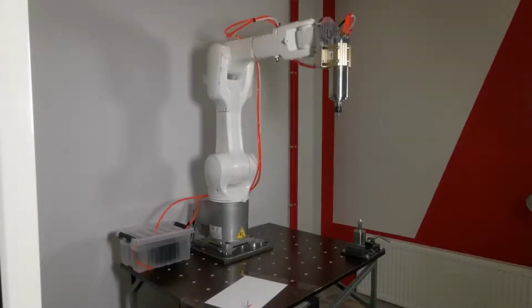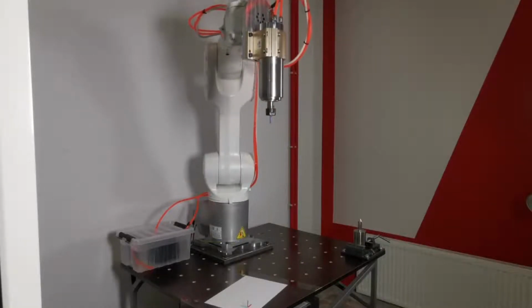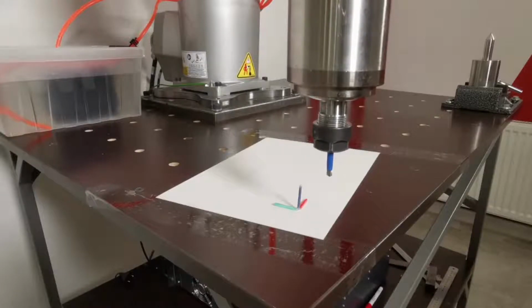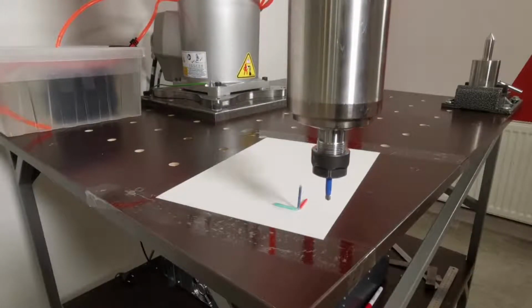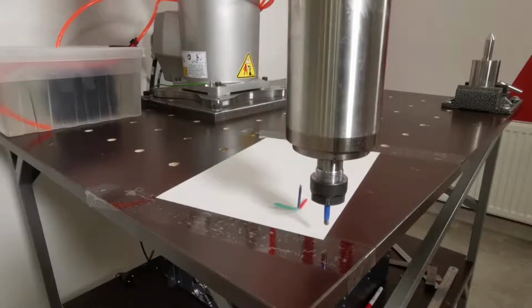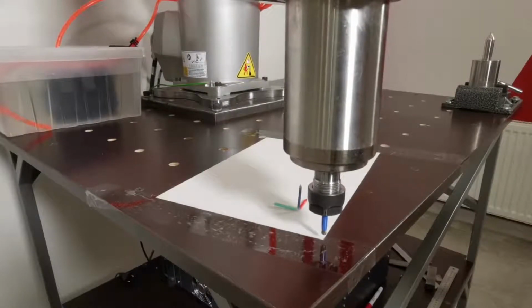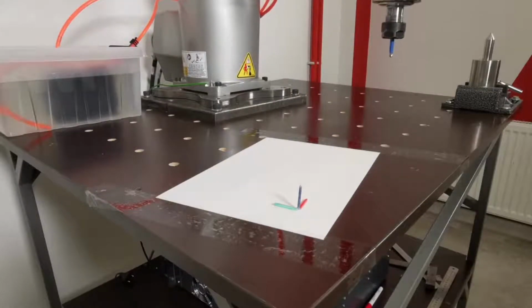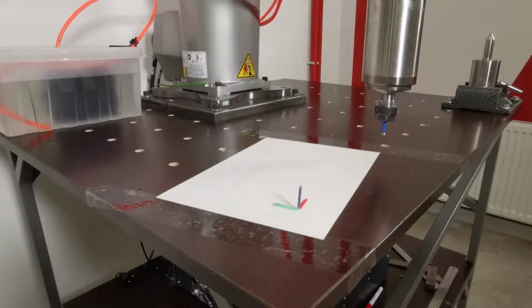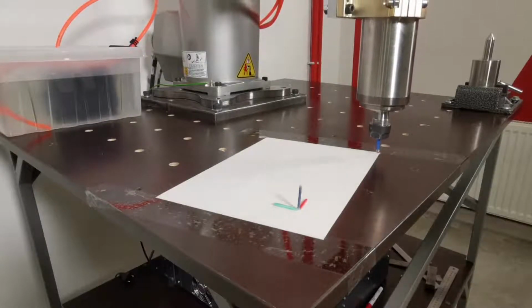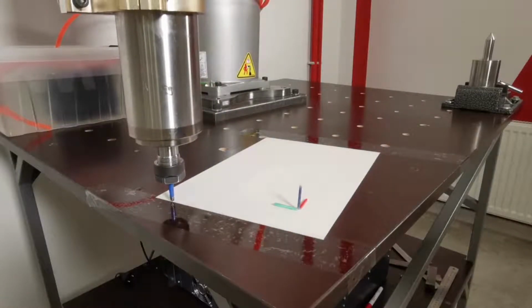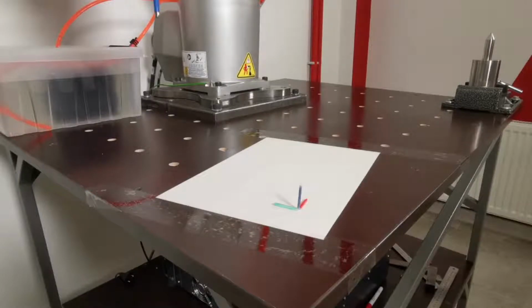Note that calibration is carried out with an already calibrated tool. It's very important. You must put ABC values for the tool you are using during the base calibration. We use base calibration by 3 points. We defined the workpiece coordinate system earlier, and you can see it's on the sheet. First of all, we direct the tip of the tool to the coordinate system origin. After that, we define the x-axis direction, and finally we define the y-axis direction.